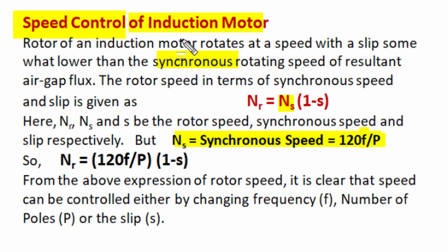Now due to electromagnetic induction and the speed difference between the rotating rotor and rotating magnetic field, currents are induced in the rotor, and those induced currents interact with the rotating magnetic field and the rotor starts rotation by electromagnetic torque developed in the rotor in the direction of synchronous speed with a certain amount of speed difference, and that speed difference is represented by slip, and for S amount of slip, the rotor speed NR in RPM is given as Ns times (1 minus S).